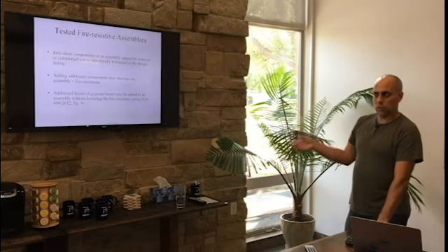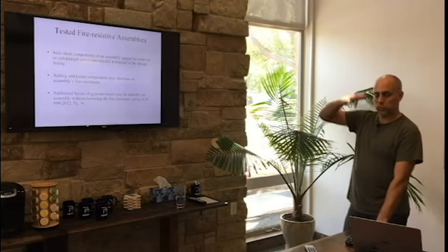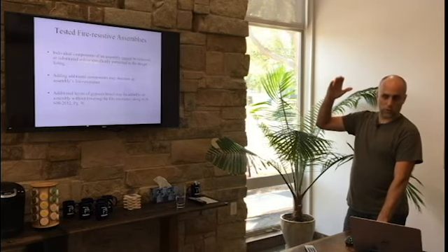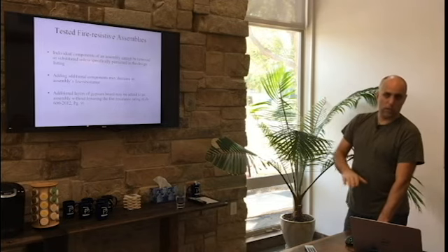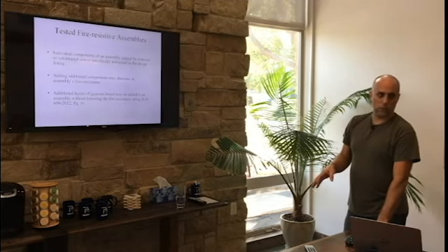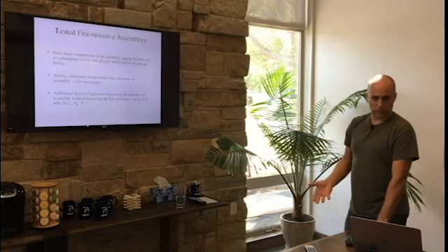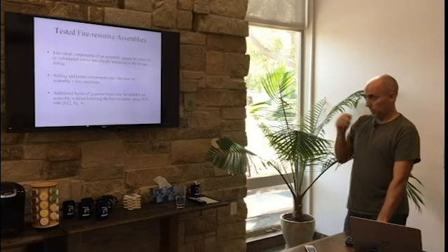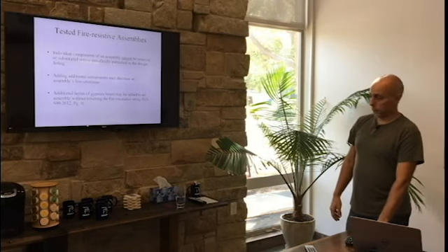A good example is in some assemblies, in the roof ceiling assembly, if you put the insulation against the roof deck, it has one requirement for the construction. If you put it against the ceiling, it has a different one. The channels are spaced closer together. Why? Because it heats up the ceiling faster. So depending upon what's in there and where it is in an assembly, it can affect the fire resistance.